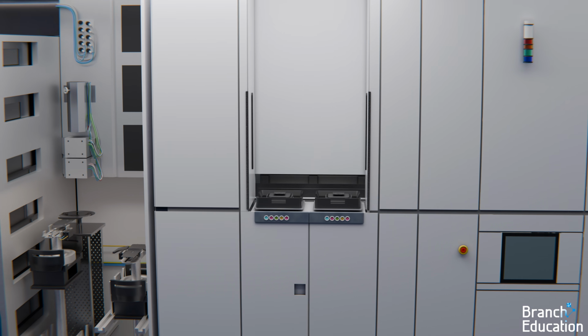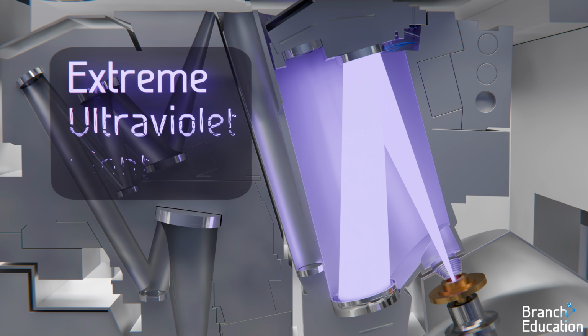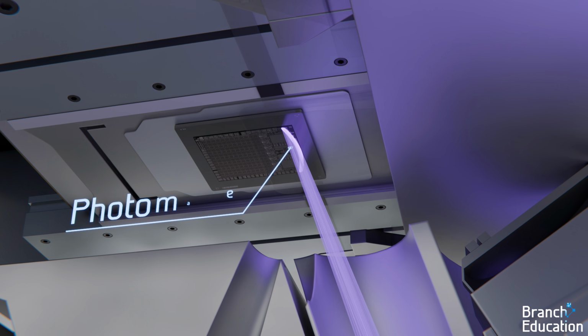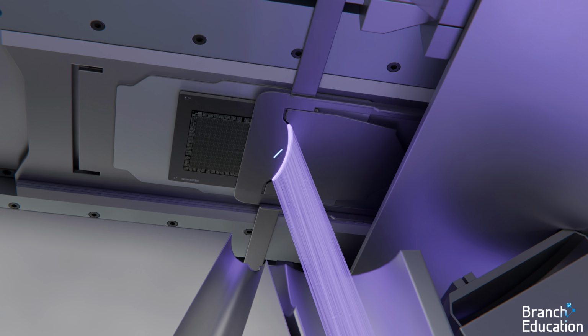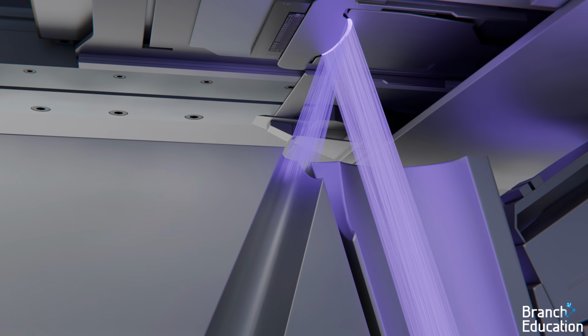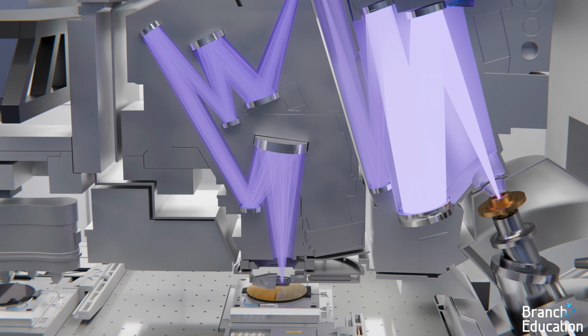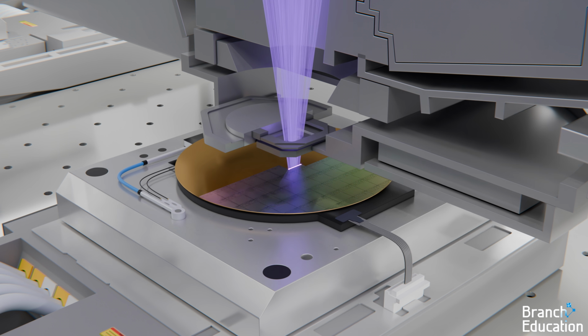The wafer then moves to the photolithography tool, where EUV, or extreme ultraviolet light, is projected onto the photomask, which is also called a reticle, but typically just a mask for short. When EUV light hits the mask, the patterned information is imprinted in the light, and this imprinted light then bounces off a set of mirrored lenses in order to project a focused and scaled-down image of the mask onto the wafer.